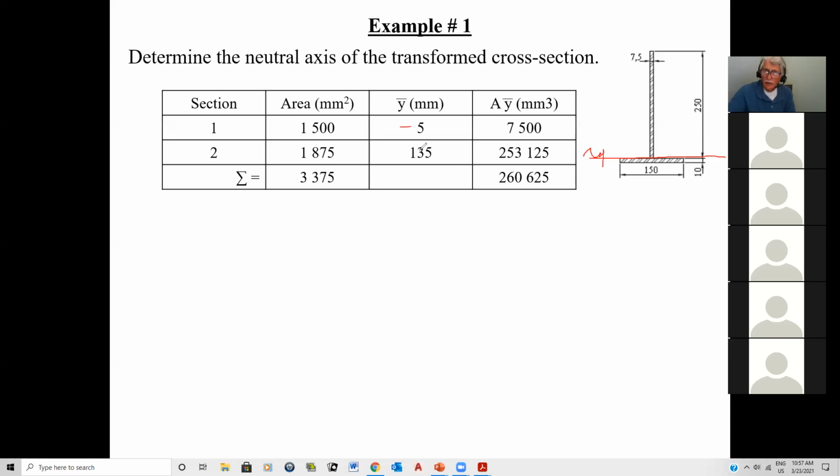So guys, you are starting to understand. In other words, you can do whatever you want. Just remember, if you're going below your reference line, it becomes negative values. The distance from the centroid of this section to your reference line becomes negative. So you can do whatever you want, but to avoid having these negative or positive values, I tend to always keep everything positive. Everybody follows?